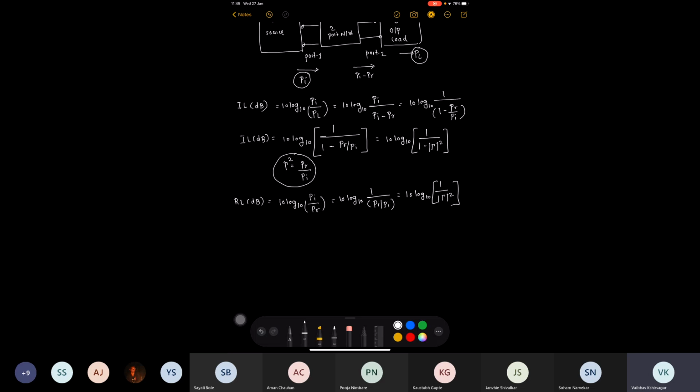Now what is the group delay here? Group delay of the filter is another important specification of the filter during the design consideration. The group delay is important for multi-frequency or pulsed signals in order to determine the frequency dispersion, or the frequency deviation from the constant group delay over the given frequency band.